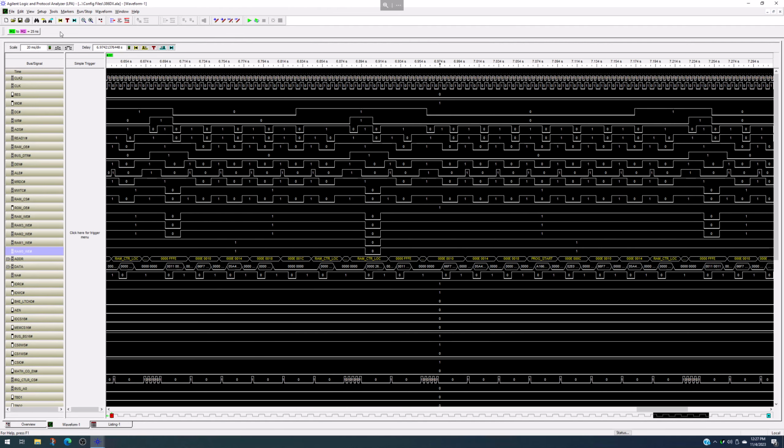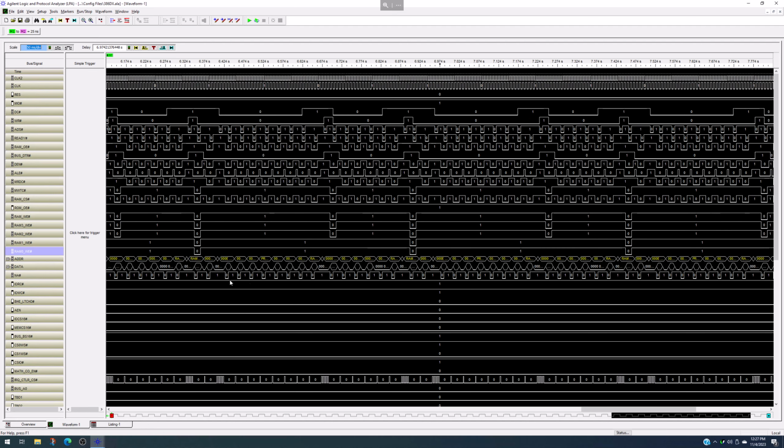And maybe let's see if I even shrink it down one more. Here I've got a program start. If that really was my start address, I could back up and tell there's a 1410. Yeah, so maybe it is pretty close to 8 is where my program is looping back to. But then I've got my program start. I'm doing something with RAM. I'm doing something with RAM. I'm doing something with RAM. Program start. So basically, I think this is my program starting. It's going to read the RAM, write the RAM, read the RAM, and then we get back to program start again or something close to that.